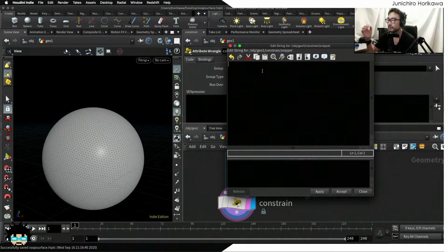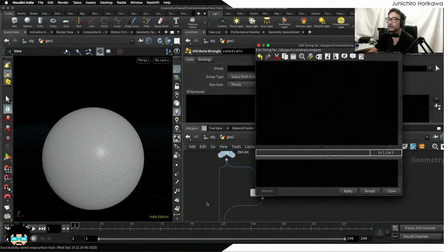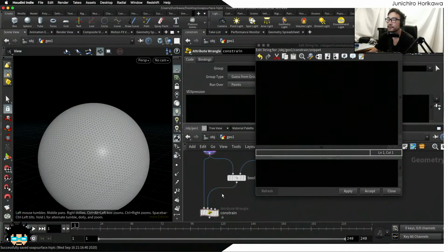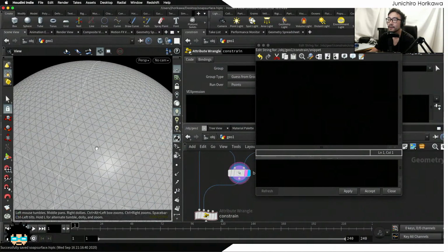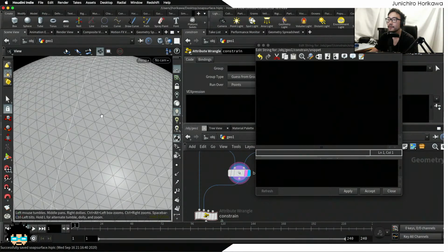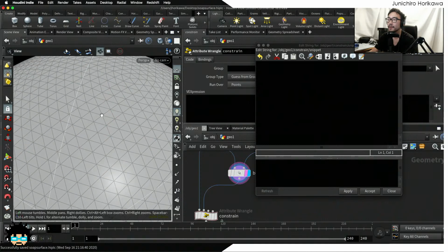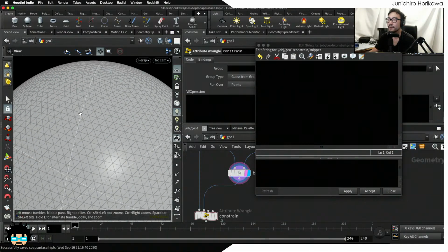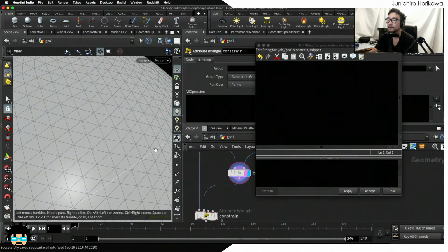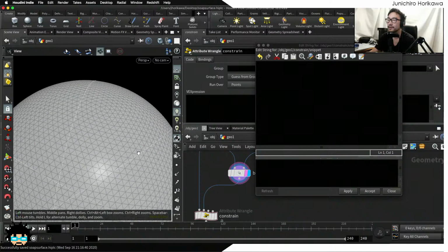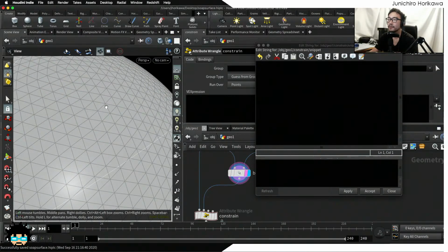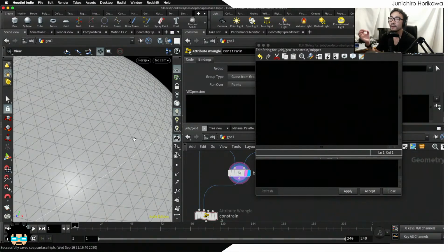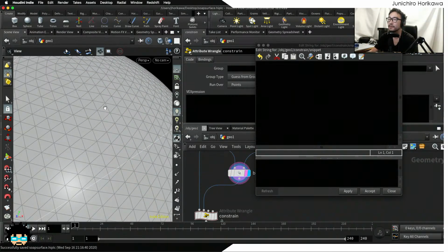First of all, you need to determine the distance from each point on the sphere to the closest point on a constrained edge. For example, for this point on the sphere, the closest point on the edge is somewhere around here, right? And for this point it is right here. And for this point, probably this point is the closest point on the edge. What you want to do is calculate the distance between these two points, then use that distance value to evaluate whether the point on the surface of the sphere should be fixed or not, depending on how far it is from the edge.